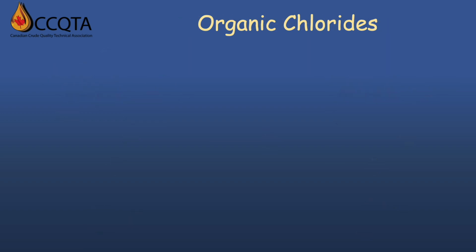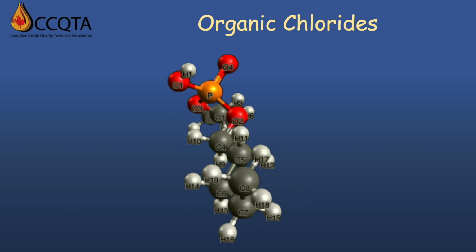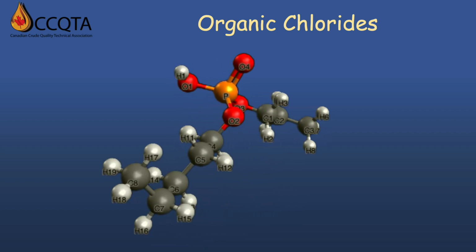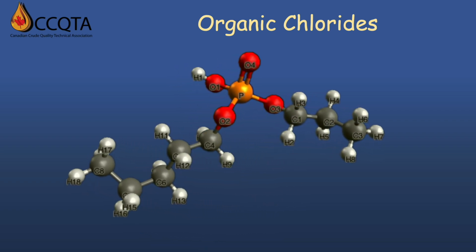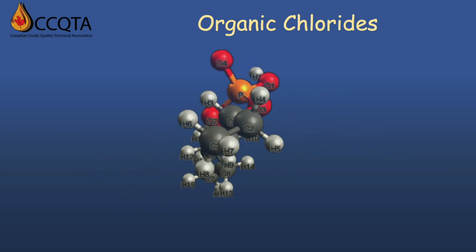In the past, oil-based well fracturing normally employed dialkyl phosphate esters as the active ingredient in the frac gellant. This illustration is an example of dialkyl phosphate ester. Note the 2 hydrocarbon chains of different lengths. These are adjusted by the chemical manufacturer to achieve the required gellant properties.